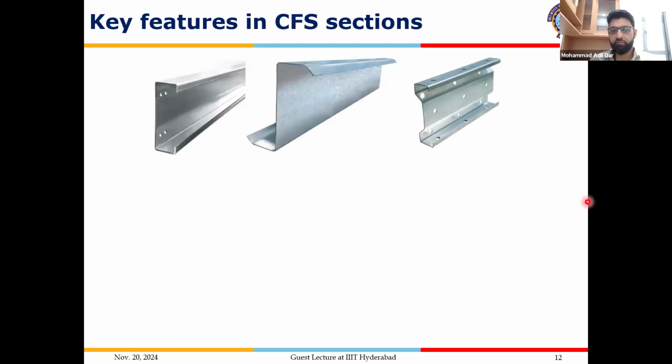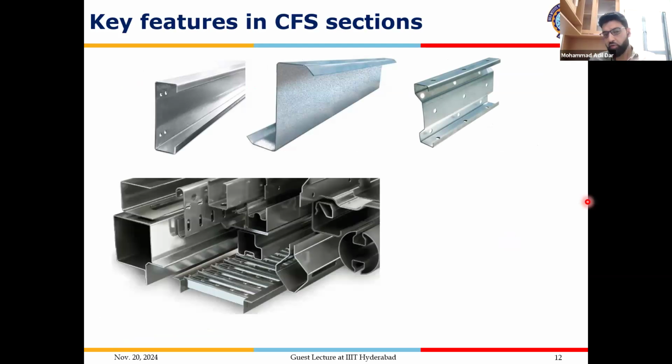So we have thin sections, which result in very accurate detailing. The offsets are much lower compared to hot rolled steel, where you have thicker sections. Because of their thin-walled nature, they are galvanized from a corrosion resistance point of view. As a result, you get a much better finish than a rough hot rolled steel section. In most cases, it may not require any surface treatment, and aesthetically they do not cause any displeasure, and architects sometimes prefer such finishes for aesthetic considerations.